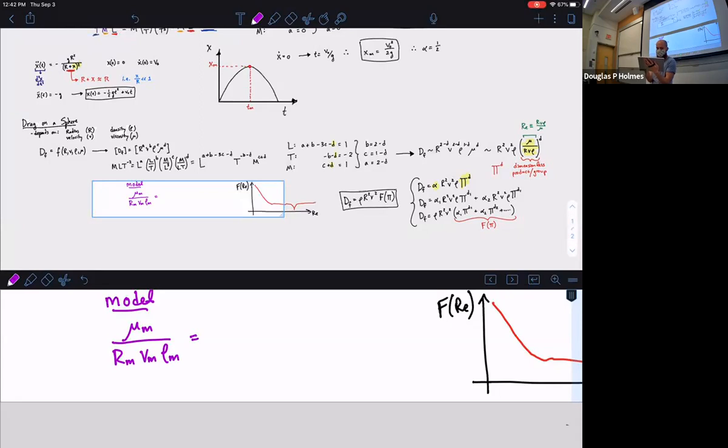This is the one that is the viscosity, radius, velocity, and density of the system that I'm actually going to use, the thing I'm actually going to build to scale. And just like you've learned forever ago with things in geometry, like similar triangles, where you can take a small triangle where all the angles are known and scale up that triangle to make all the sides bigger, and you'll still know that the angles are the same as you scale. That's geometric similarity between those properties. This is an example of physical similarity. So I can take this set of equations here.